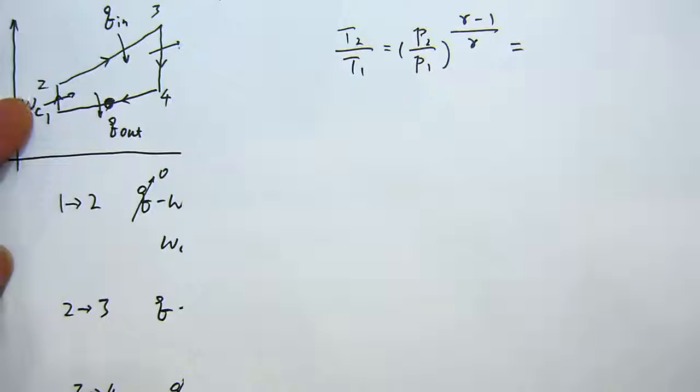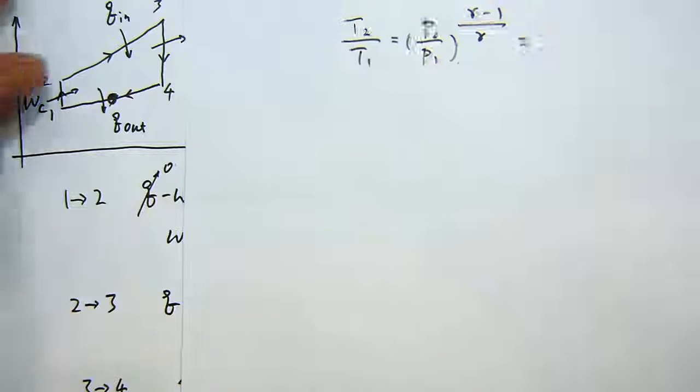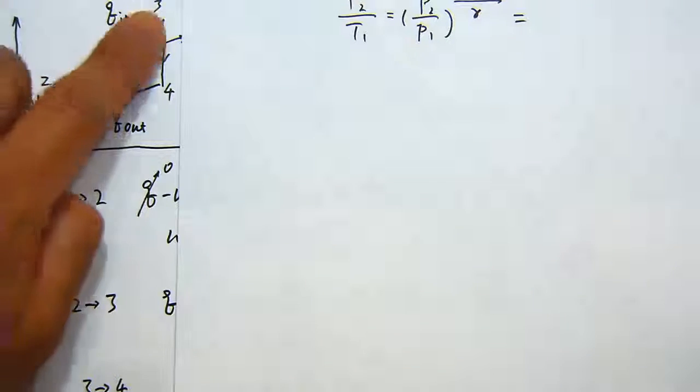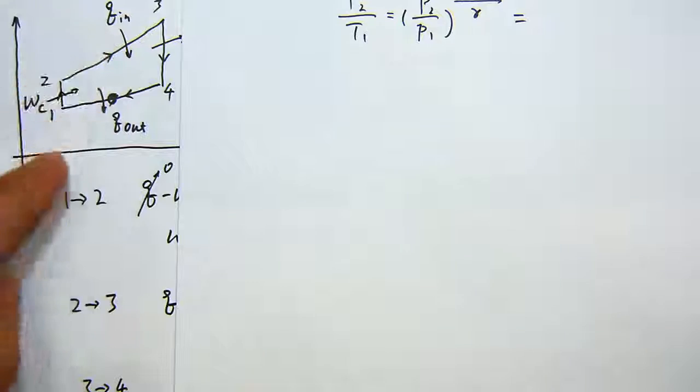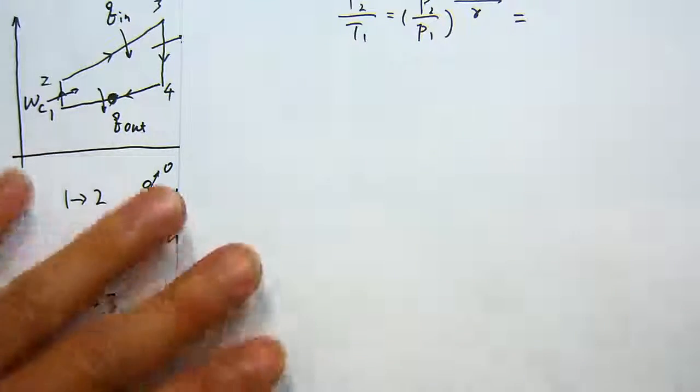We mentioned that the cycle, not only this gas turbine cycle, but later on, when we're looking at refrigeration and the steam turbine, basically all these cycles are working between two pressures, a high pressure and a low pressure. So particularly here, we deal with only two pressures. The P2 has the same pressure as the P3, and the P4 has the same pressure as state 1.